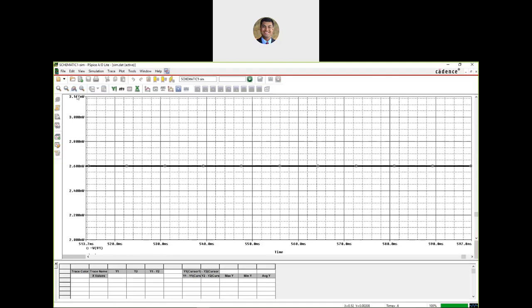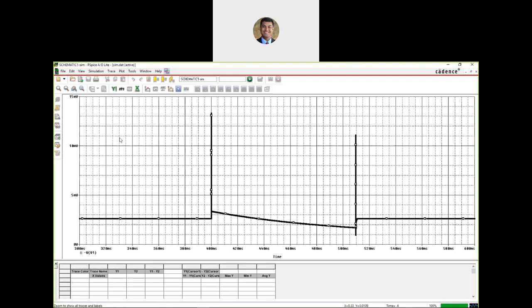So as you can see, the average power consumption of my circuit when I use 10 kilo ohm, and all of these are for 10 kilo ohm, this is circuit 2, 10 kilo ohm and 10 microfarad, is going to be 2.6 milliwatts. So what you would do is you would have another simulation in which you will use the 100K and the 1 microfarad capacitor, run a similar simulation, look at the average. So you're averaging it for the same amount of time, say 300 milliseconds.